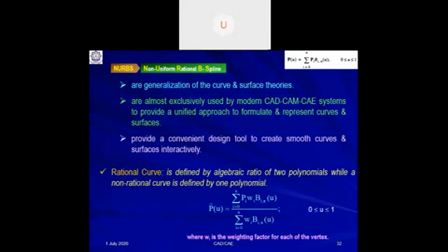The main thing is that using a particular generalized equation, by changing the different constant parameters, you can represent the same curve, and it can be used for cubic spline, Bezier, or B-spline, only by changing the different constants in this ratio of two polynomials.